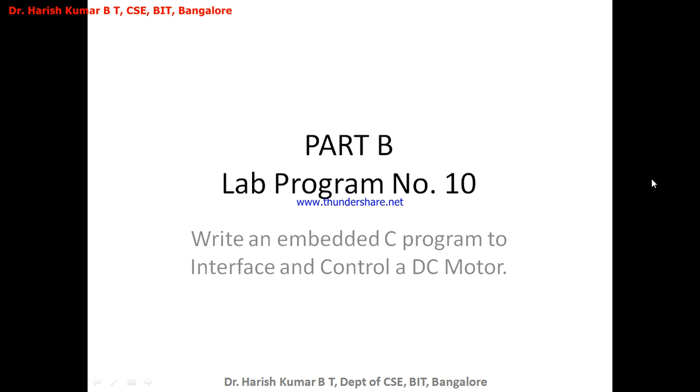The C program was written in the Keil IDE, compiled, and the HEX file was generated, and the same HEX code was written to the microcontroller in the Proteus simulator. And then in the simulator you observed how the LEDs blink. That was not the lab program, that was just a sample program.